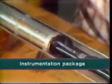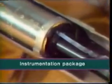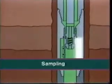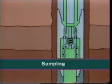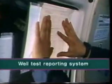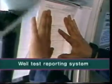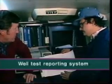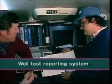It should include the pressure and temperature measuring and recording devices, as well as the wireline recommendations. The package should also include specifications for sampling produced fluids, how many samples to take, when, and where. Finally, a complete well test reporting system must be prepared to be sure that the well test procedures are communicated clearly to all persons concerned with the test, and that all test data is recorded properly and systematically.